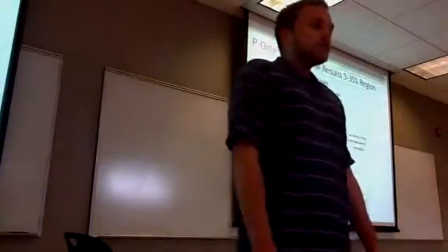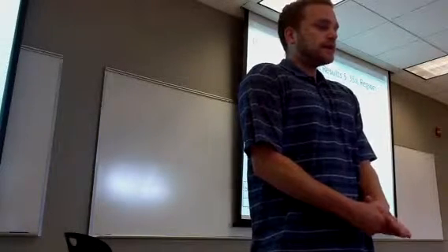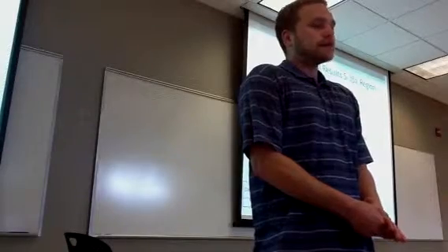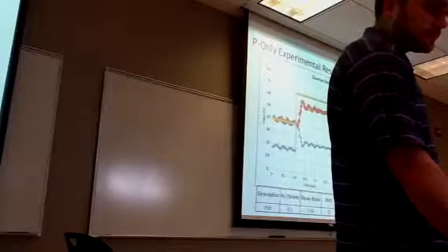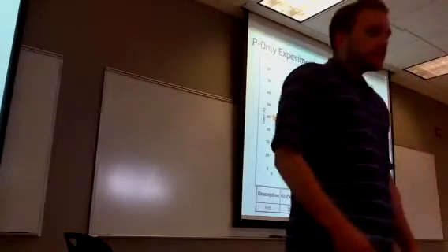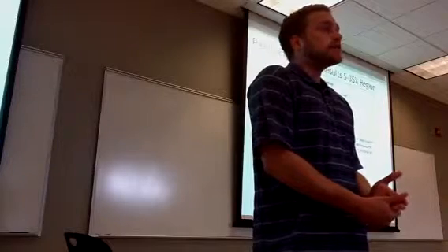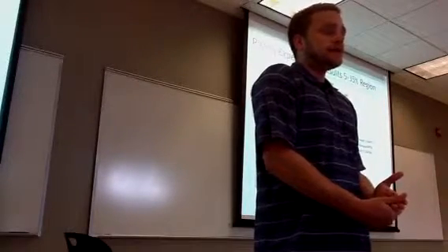Here are the P-only experimental results for the 5 to 35% region. This was with a controller gain of 0.03% per RPM, and it gave us an offset of 130 RPM. Here's a quarter decay with 0.1% per RPM being the controller gain. It gave us a decay ratio of 0.26, settling time of 1 second, and an offset of 70 RPM.